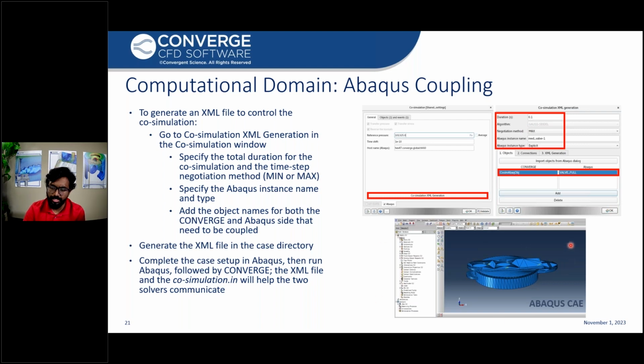I've just shown a screenshot at the bottom to show the Abaqus case setup. Again, in this case, we have a contact constraint between the suction reed valve and the seat, and we do have a stopper in the cylinder bore, as well as some contact constraint with the piston. So I had to include all this geometry for providing the contact constraint. Additionally, I provided the piston motion as a boundary condition in Abaqus, so that as the piston moves, the constraint will also be changing.